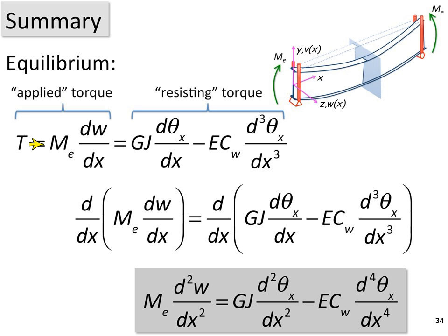And strangely enough, what we're actually going to do is take a derivative of that. And you might say, well, what the heck? That sounds pretty bad. But there's actually a good reason for doing that, because the second derivative of w is related to our moment curvature principle. So getting that second derivative is our friend here, even though it makes for a slightly uglier differential equation. So here we are now. I know you think, oh God, is this thing ever going to end? And it does. We're pretty close. So let's move to the next slide.